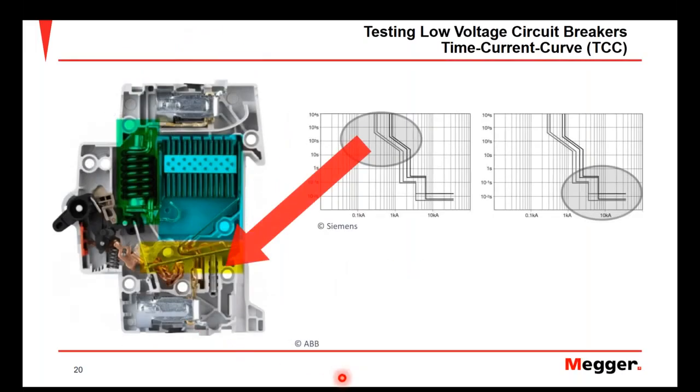So this is a physical representation of the mechanical hardware in relation to the overload element of a circuit breaker. We mentioned in the last slide that the overload conditions refer to your long time and your short time trip functions. Well, that's in relation to this physical mechanism within the breaker for the thermal protective functions.